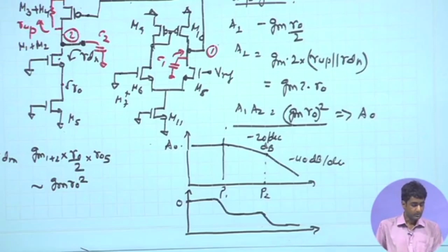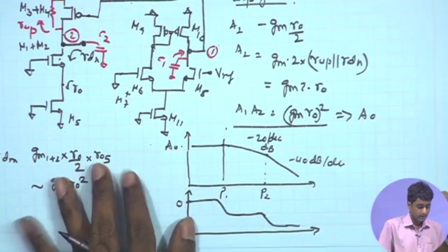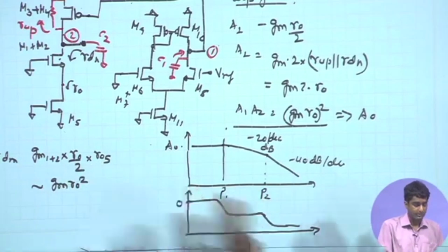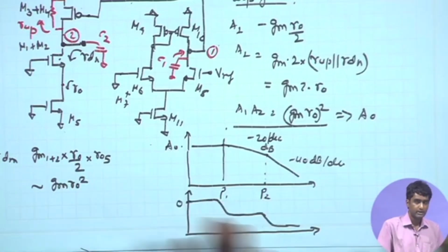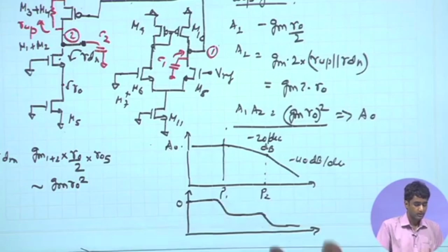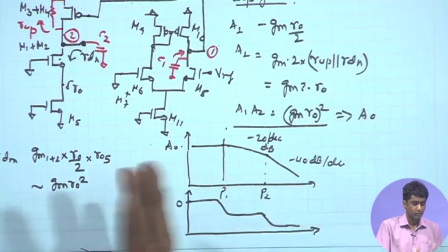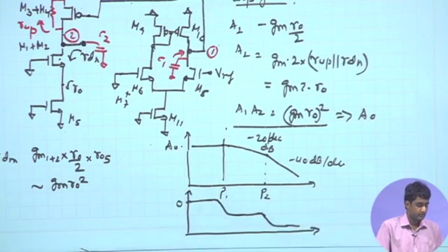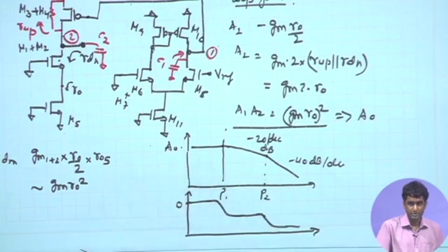And now, in order to get a stable response, we have discussed earlier that we need to ensure a good phase margin, at least around 45 degree of phase margin, so that in the overall closed loop response we do not have any ringing, and with respect to parameter variations and process variations also we have enough margin.